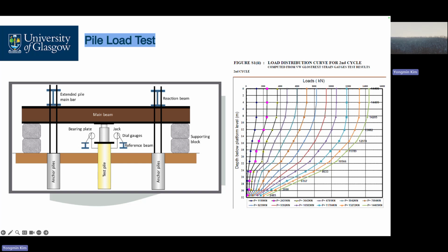Wow, this is a pile. Then apply loads. What loads? Axial load. Up to 3 times working load. Then you will get a complicated graph.